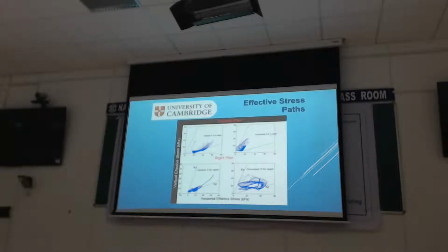They're exactly the same experimental setup. The labeling is wrong. It's doing something similar to the flexible one. Here again, at depth, you got things sitting at Kp, but at deeper depth, you got a big variation going all the way from Ka to Kp as you cycle and cycle and cycle.